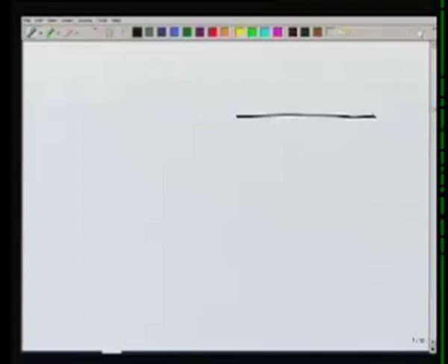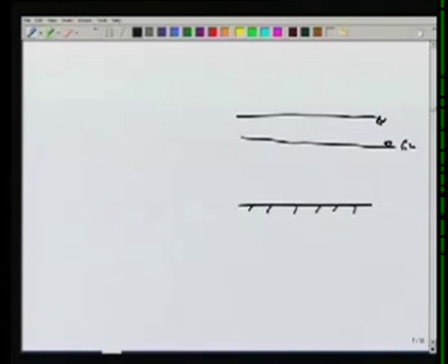So suppose we have the ground level, impermeable bed, and then there is this water table which is at a certain gradient so that the flow occurs because of this gradient. If we have observation wells here, we can note down what is the ground level here and what is the groundwater table at this point. So this will give us an idea about what is the groundwater level at this point.